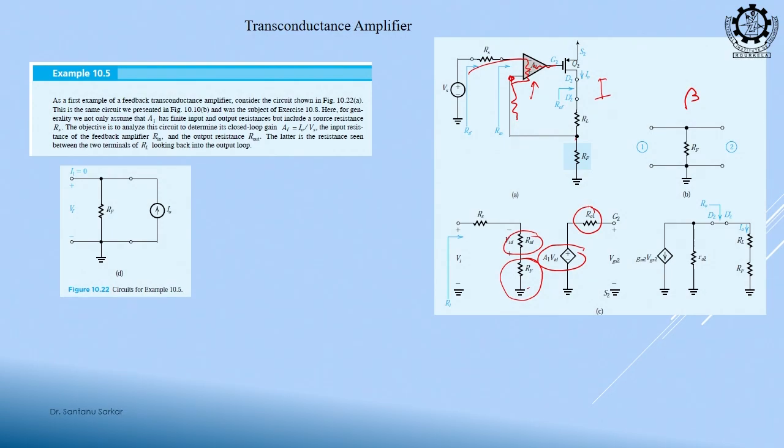So, this A is dependent on VID, this VID is this differential voltage. So, A into VID, right, and this will have an output resistance. Generally we consider this as 0, but if some value is given we can consider it, right, and this point should be connected to this circuit. What is this circuit? Again I can replace this MOSFET with its equivalent hybrid pi network, right. So, input impedance is a large impedance and this has a transconductance, right. Output is a current.